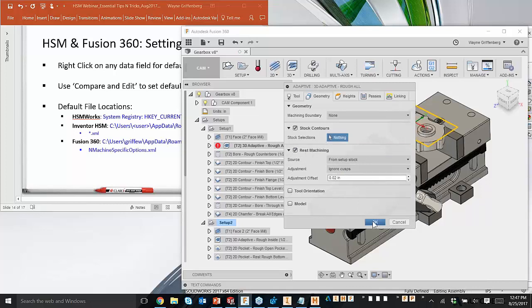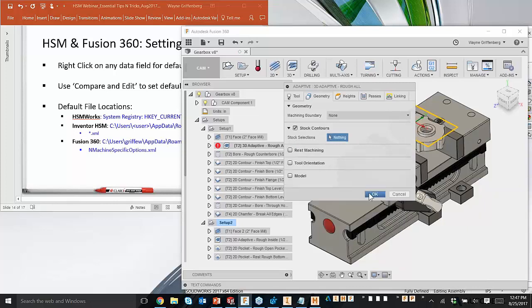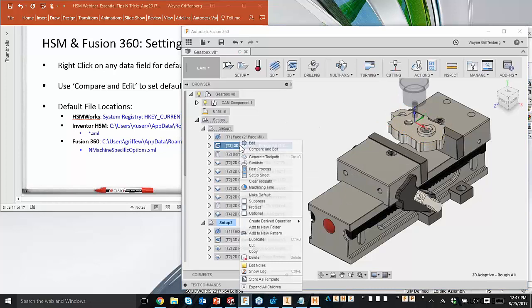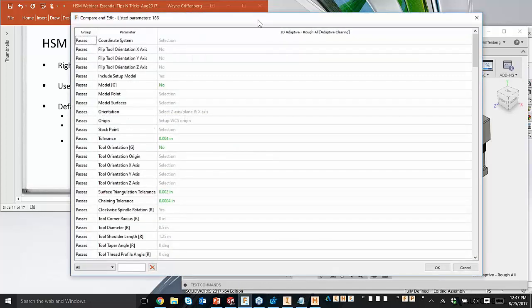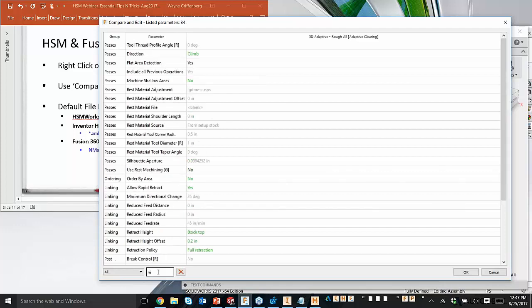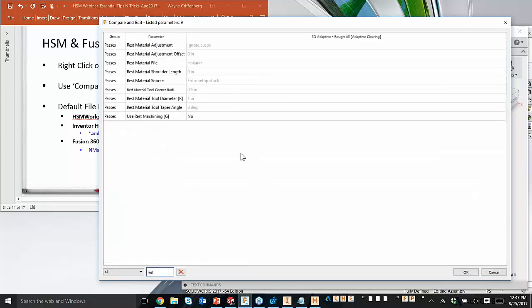So I'm going to say OK. Right now it's checked on. I'll leave it off the way I want it. And the one way we can set that default is if you right-click and go to Compare and Edit. And we'll take a closer look at what Compare and Edit can do. But I would go into this interface as a tip. And I always want that rest machining on. So I'm going to filter. I'm going to look for rest machining. And over here I said...